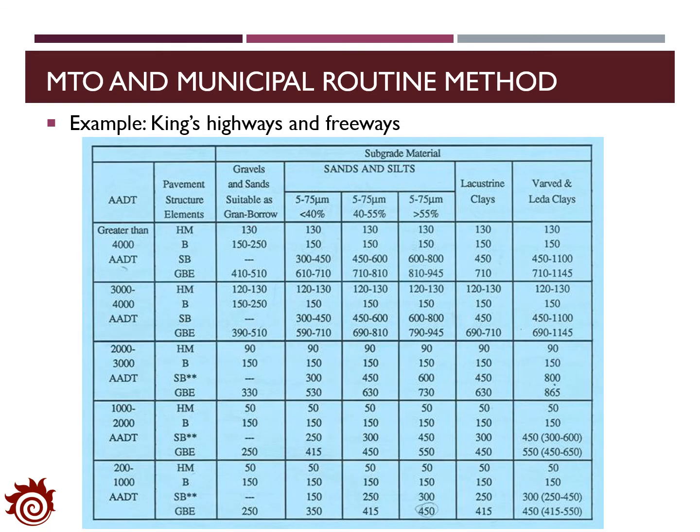This table shows the structural design guideline for the flexible pavement along Kings Highway. In this table, the impact of the drainage and frost has been considered. Basically, in the design, we need to consider two variables: the average annual daily traffic and the subgrade material property.